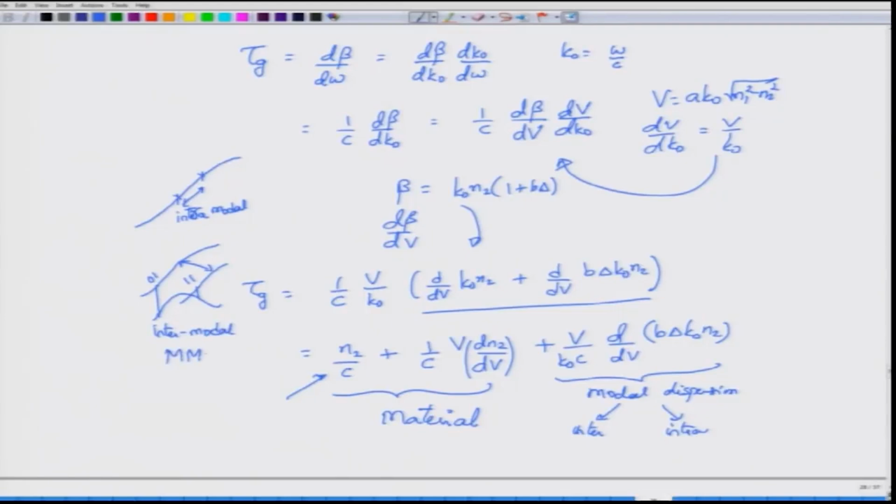Intermodal dispersion is quite common, and in fact is one of the major problems in multimode fibers, whereas intramodal dispersion, sometimes called simply chromatic dispersion, is an important parameter in single-mode fibers. But our formalism would simply want you to know what beta 2 is, and therefore does not really depend on whether you have applied it to a single mode fiber or a multimode fiber.